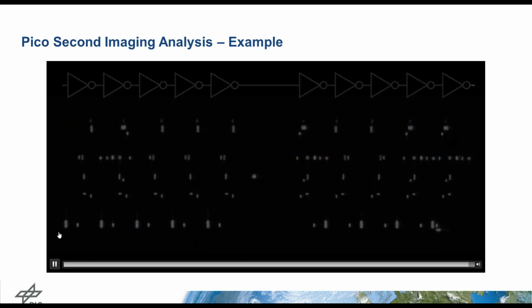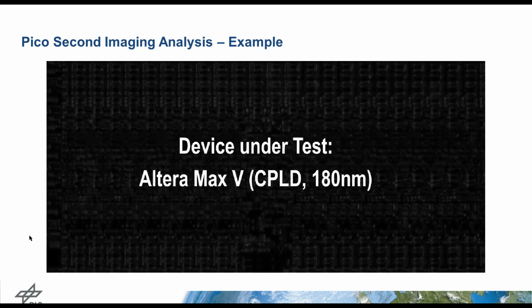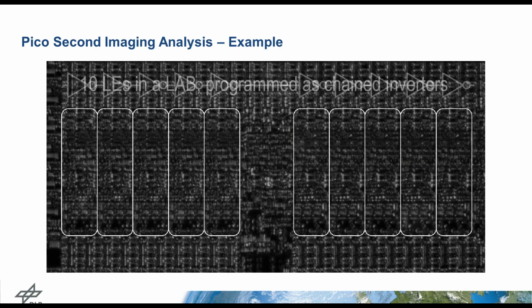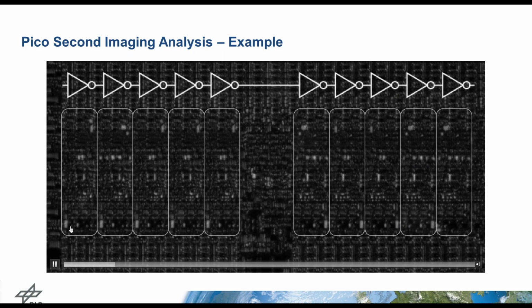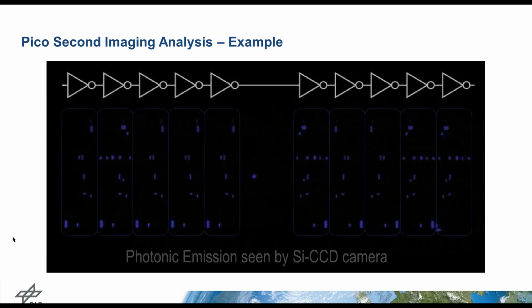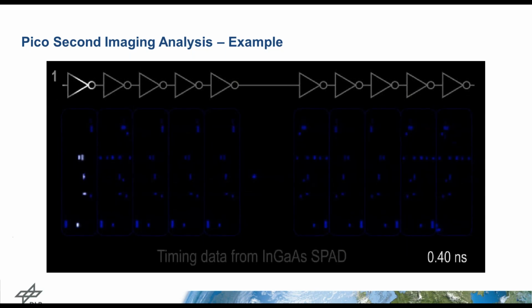And what is also quite interesting here is that you have seen a different size of the PMOS and the NMOS. The big transistors are the PMOS, and the small ones are the NMOS transistors. This is because the mobility of the electrons in an NMOS is 3 times higher than of holes in a PMOS.